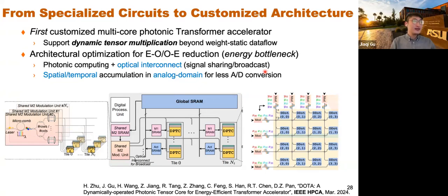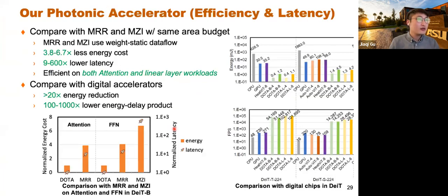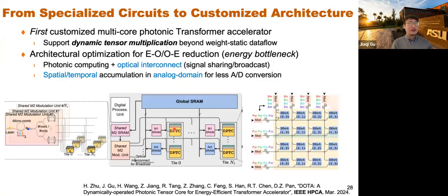Yeah, right. So different designs have a different breakdown. I didn't show the result here. So for this architecture, ADC power is very high. The reason is the frequency is too high, and also the resolution. If you use 8-bit, the ADC power is very high, and it takes almost definitely beyond 20%. I don't have the actual number, but the number is significant. That's why we want to use this temporal integration to reduce the ADC frequency.